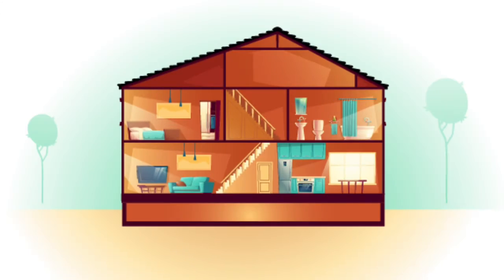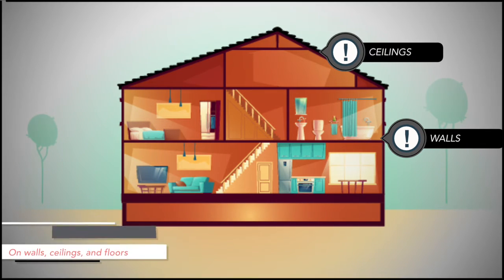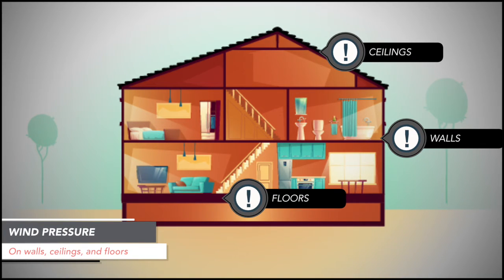of heating and cooling a home. The walls, ceilings, and floors we build are constantly subjected to air pressure differences, resulting in outside air infiltrating into the building enclosure, while the inside air is exfiltrated to the exterior. These pressure differences can be caused by wind loads, which can vary by height, exposure, and site conditions.